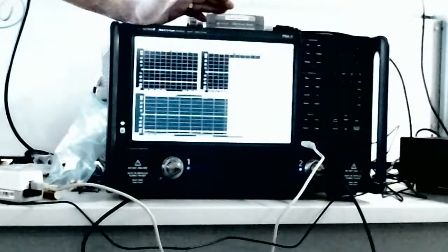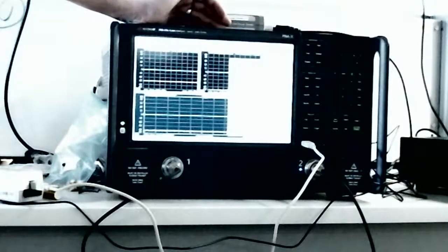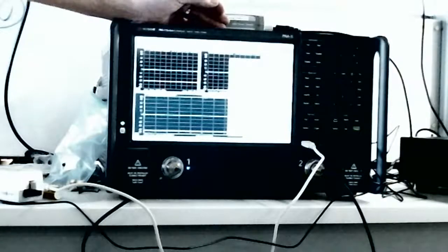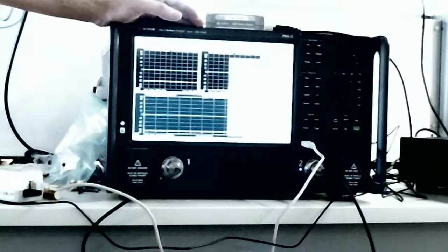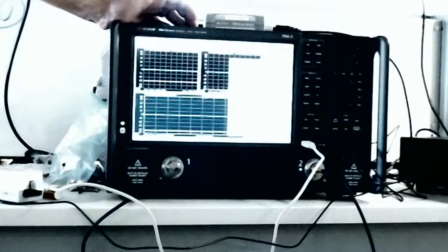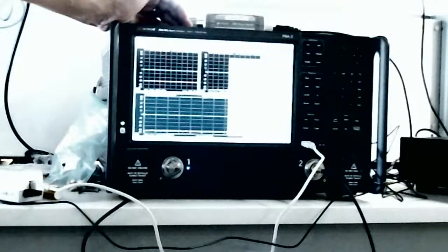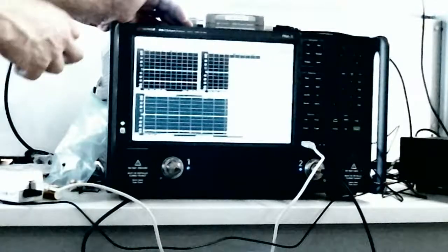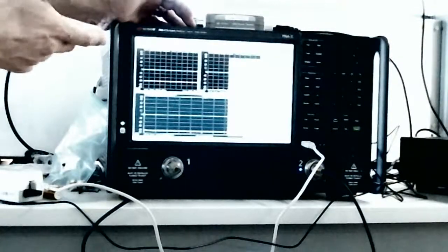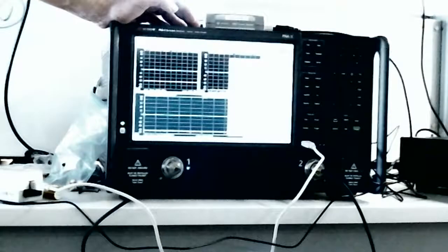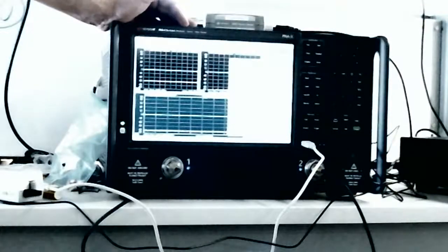And if you have 75 ohm, which might be the most common if you're doing some kind of cable TV application. If you're using the balanced mode, for example, the differential impedance might be 100 ohms, but effectively the port impedance is still 50, so it doesn't matter for that application. But if you have a balun or some other kind of impedance matching network, you can say, well, actually, based on this balun that's 50 ohms to whatever the system impedance is, you can use port Z and actually put a full complex impedance in there if you know exactly what you're going to be measuring.